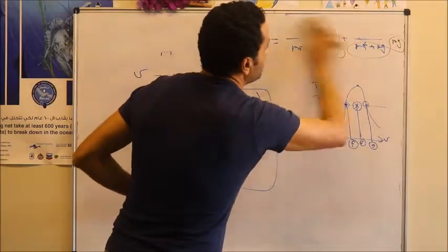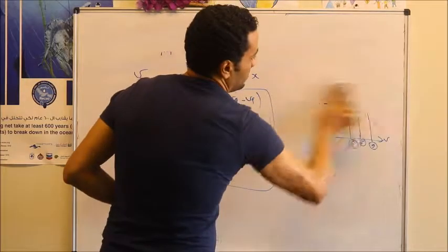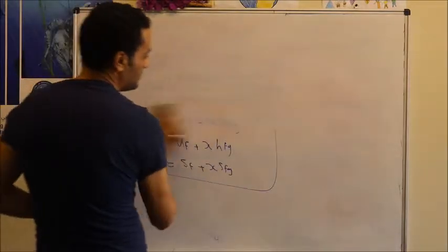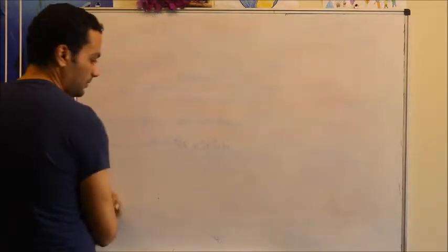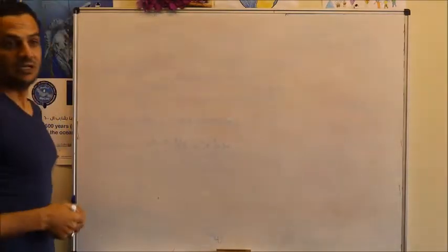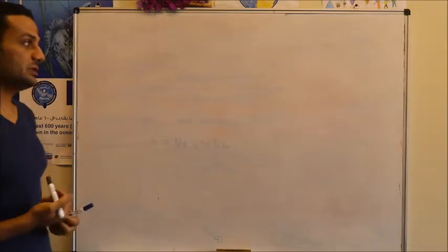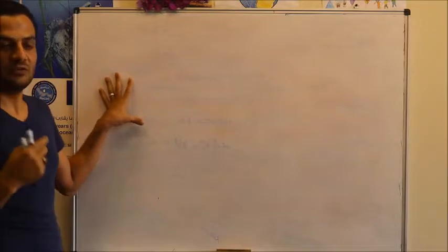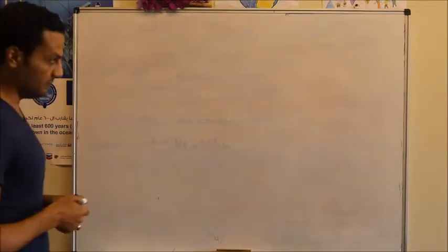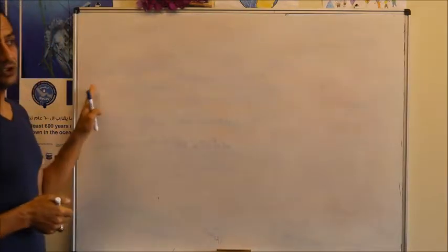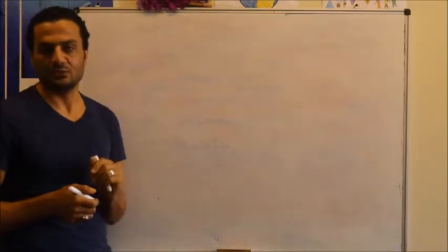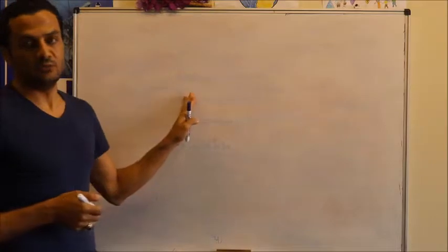What will be given for you in this case is pressure or temperature with one specific property. As we said, in the saturation mixture zone, all points in the saturated mixture have the same pressure and the same temperature. So pressure and temperature are not independent properties. And to use the table, you have to have two independent and intensive properties. So if pressure and temperature are given, the state is not actually saturated. We are not in the saturation mixture zone.